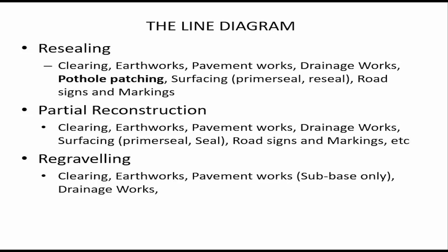Then the last activity is regraveling, which entails clearing, earthworks, pavement works up to sub-base only, and then drainage structures. Regraveling, we end at sub-base. That's because the base material, the PI is lower than that of sub-base. So if not sealed, it will disintegrate quickly. And the sub-base is more cohesive. That is why we terminate the regraveling at sub-base level.